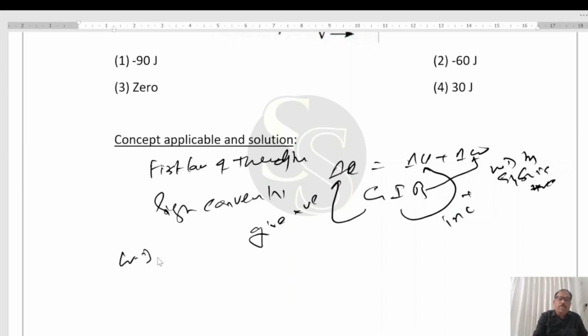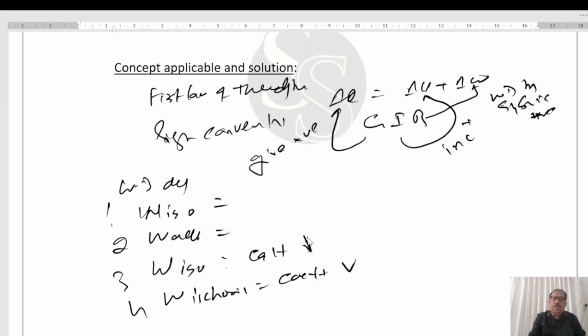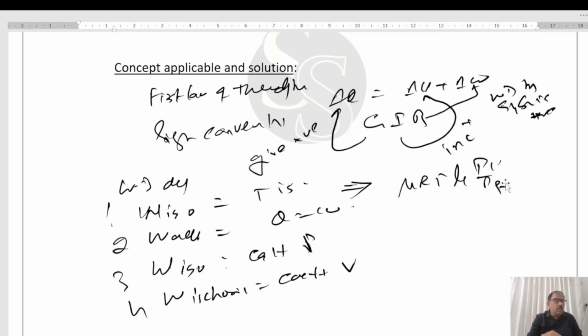Now, there is also further information. Work done during isothermal, adiabatic, isobaric and isochoric processes. Isochoric is constant volume, isobaric is constant pressure. In the isothermal case, the temperature is constant, and work done is mu RT log of Pi upon Pf, the initial pressure over the final. For adiabatic, W is mu R (T2 minus T1) upon (gamma minus 1).